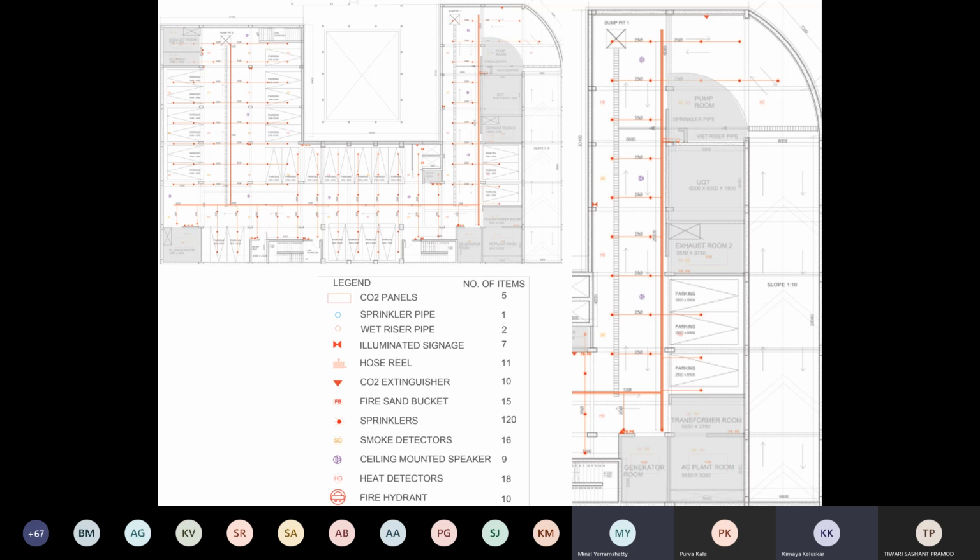Okay. By the way, guys, we generally don't calculate for exhaust because exhaust is something where I'm not providing anything, I'm just taking away. So it doesn't matter. I don't really have to think about proper velocity and proper draught and everything. I don't have to bother. It's just taking away. But when I'm supplying it, I have to take care whether every nook and corner is supplied, whether it is supplied in the right quantity, whether the air change is happening or not.